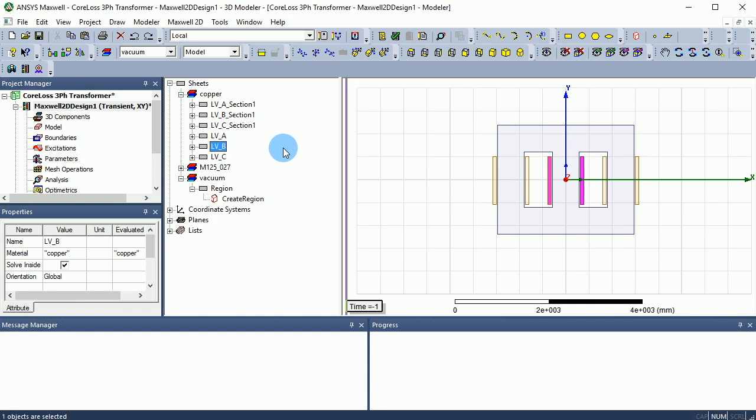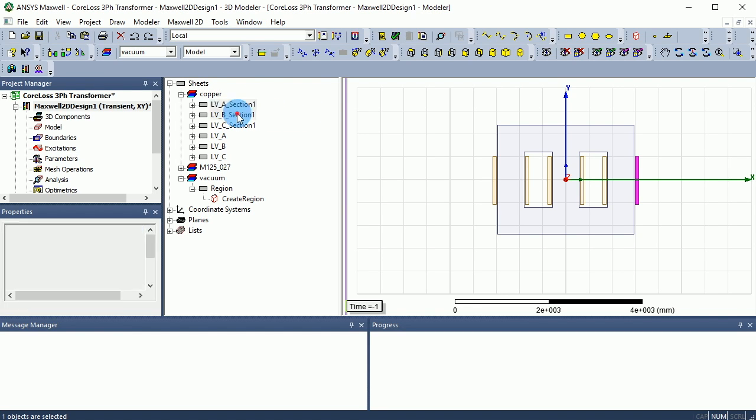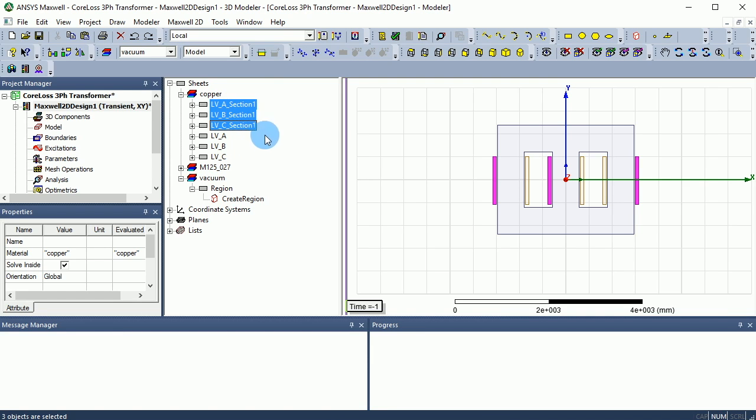That means that these are the coppers that we have for the coil, and the ones on the top are the cross sections that we defined on the 3D sections. Now you can see that these are extra, so you can easily press and hold the Control key, select multiple of these cross sections, and get rid of them by selecting delete.